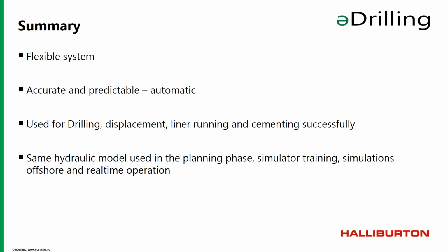the operation. That's built into our system, also based on the modeled parameters and what we expect to see during the operation. And by using a model like the well balance, you are actually modeling what kind of flow out you should have as well. So if you have a good Coriolis meter, it's very easy to compare, because the model takes into account all the dynamic effects like temperature and oil movement.